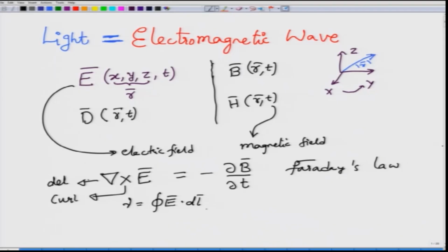This is your familiar KVL equation. So, there are no sources, the magnetic field is not changing, and as you pass along the loop, you would see that the total EMF induced would be 0. There might be some elements where the EMF is increasing, but there will be some elements where the EMF will be decreasing, with the net result that in the static condition the EMF will be equal to 0, but not so when there is a magnetic flux.